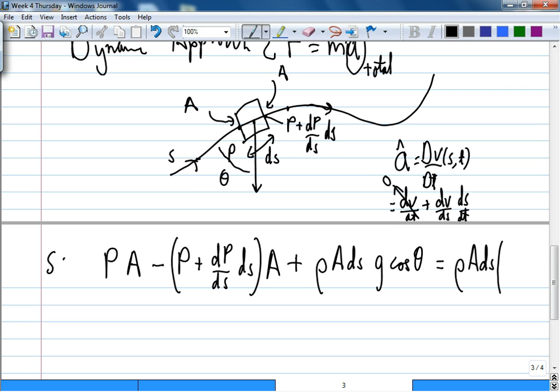But if the fluid is 1 meter per second at this point, at some later time it's still 1 meter per second, no change. But this other point doesn't need to be 1 meter per second. For example, it could be 2 meters per second. So when the fluid travels between here and here, there must be acceleration, correct or not? That's captured in this spatial term here. So the fluid is accelerating.